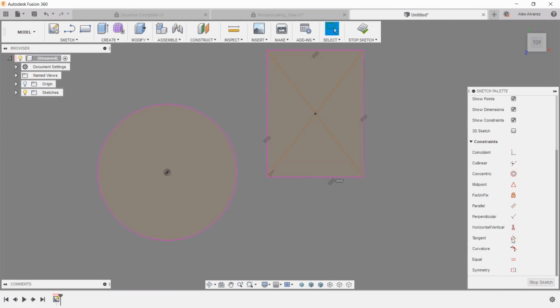If you go ahead and click on horizontal, vertical, let's click on that center point here. Now, again, what do we want? We want the center of this line here. And notice as we hover along the line, it doesn't really give us that famous little icon here, right? The triangle that's indicating the midpoint. If we hold Shift on our keyboard, take a look at that, right? So it gives us that midpoint of the line. Click on that, and it automatically constrains it to be horizontal, right?